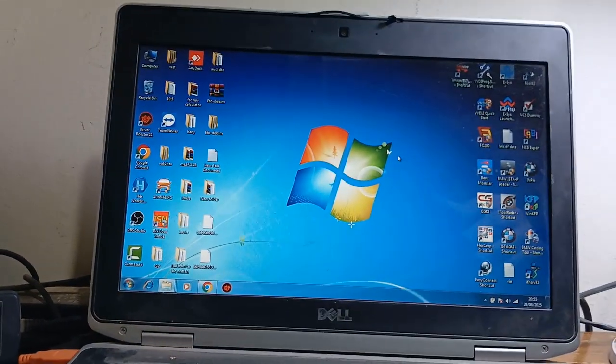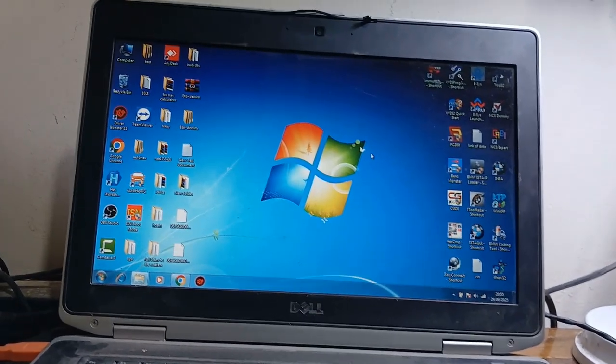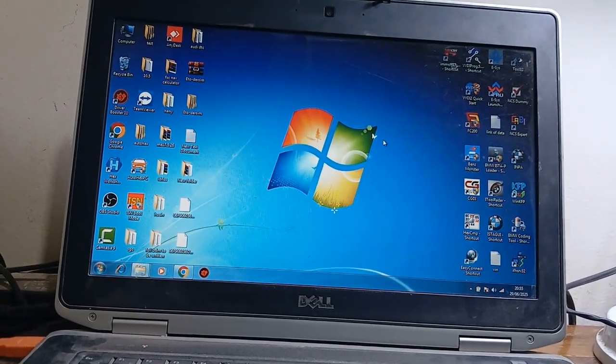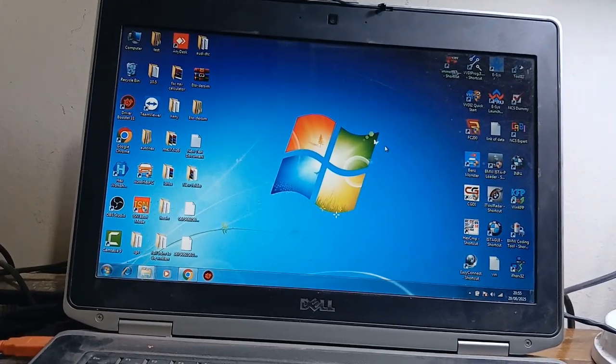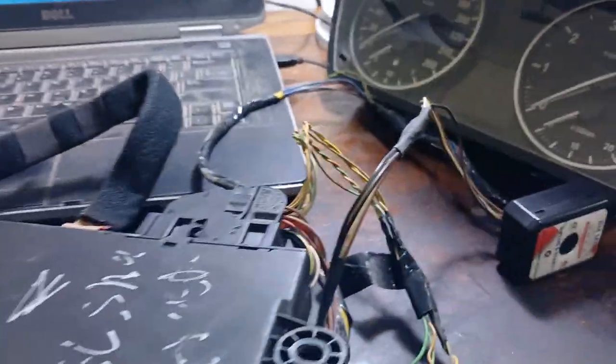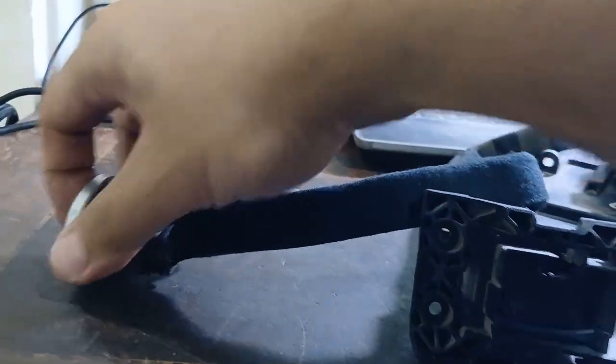I have an option to repair Eeprom on CGDI BMW and other issues, but I will see if it will be able to communicate with this one or not. And again, after writing a good flash, power supply is on, still nothing.